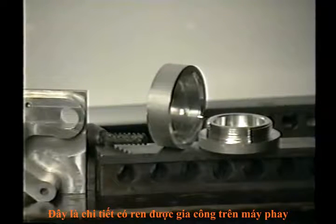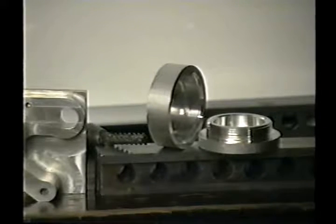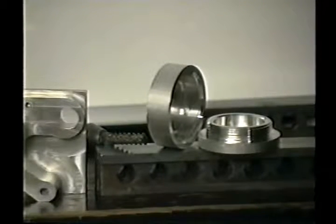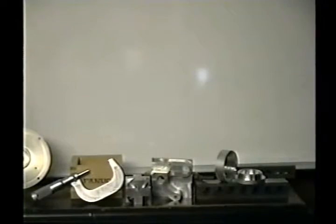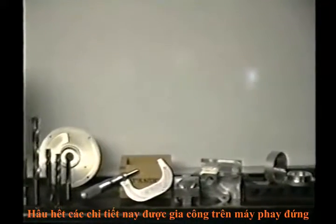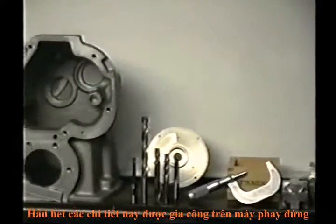This is a thread milling part, and the cutter you see is a thread milling cutter. To be able to do this, the machine would require a feature called helical interpolation. All of these parts were made on a vertical machining center.